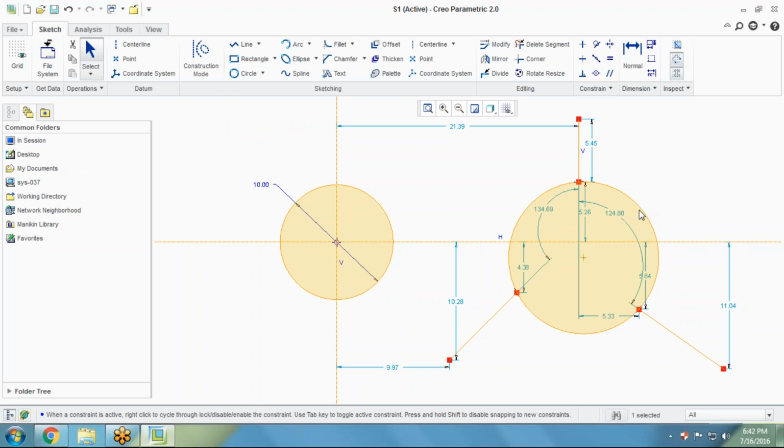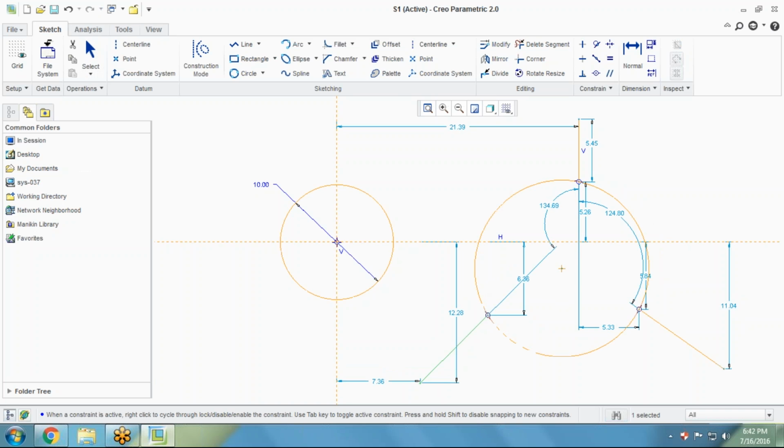And we will see the circle has been created accordingly. And after that, 3 tangent section. So you will see here we have one entity is this, second one is this, and third one is this. I want to create some circle here. I don't know what the size of that particular circle is. I want the tangential connectivity between all. One is this, second is this, third one is this. So you'll see the circle will be adjusted accordingly within the 3 entities.